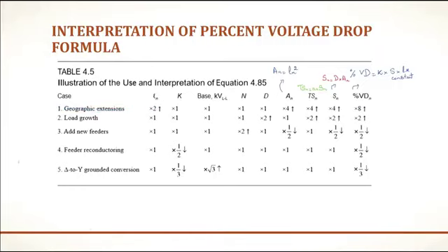Now let's consider the second case, that is load growth. So what do you mean by load growth? Definitely the length of the feeder will not change. The value of K will not change. The base voltage will not change. The number of feeders will not change. Load growth means you are increasing the load density. So load density will become double.